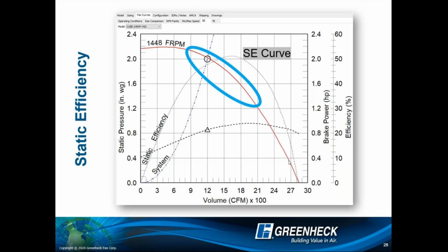Well, not as much. When I'm operating in this efficient zone for this fan, I'm going to get quieter operation. I'm going to make that dollar for electricity stretch farther, less wear and tear, right? If I'm operating in an inefficient place for this fan, louder, vibration will increase, right? Costs will go up for operation.